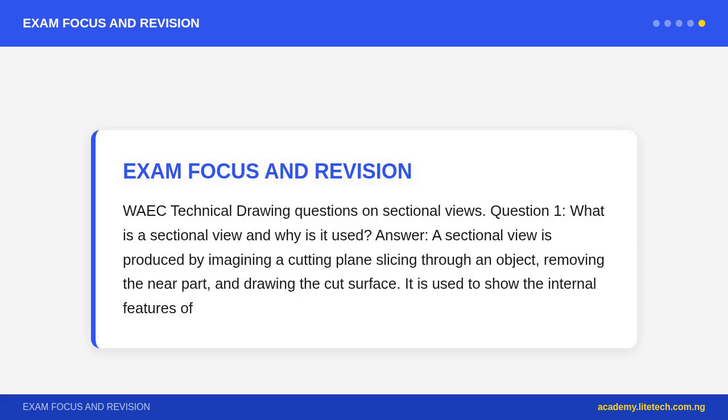Question 5. On what type of drawing would you use a half section rather than a full section, and why? Answer. A half section is used on symmetrical objects, e.g. a circular flange, a pulley, a shaft with a central bore. It is preferred over a full section for such objects because it shows both the external profile, in one half, and the internal features, in the other half, within a single view, providing complete information without requiring a separate external view.